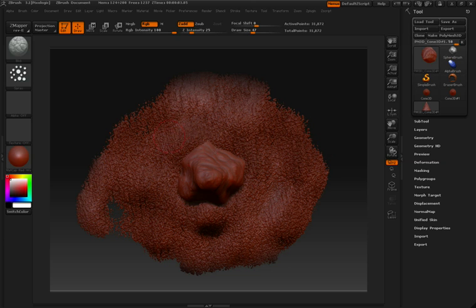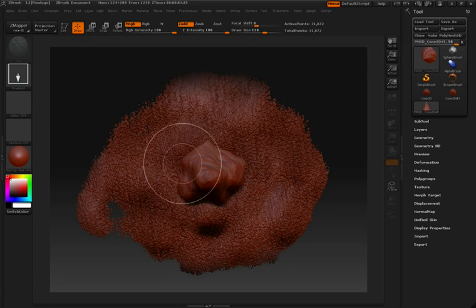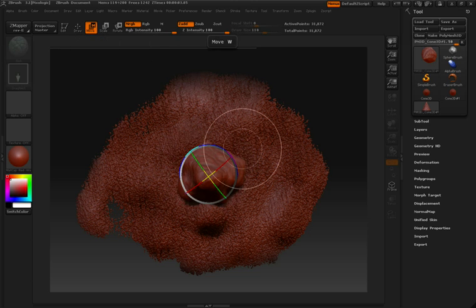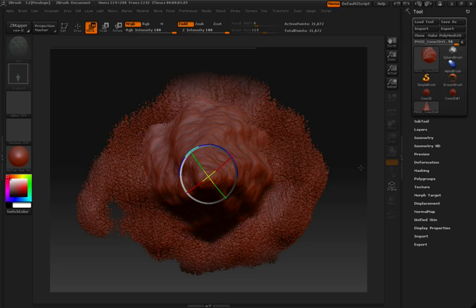Now that that's positioned, again I'll click Edit to drop it to 2.5D state, and then click Move. In this Move state, I'll simply click in an empty area. I'll click and pull towards me. As I do that, we're pulling it out from the underlying pixels. So you can sink it back as far as you want or pull it forward. I'll just get it blended in with the surface.